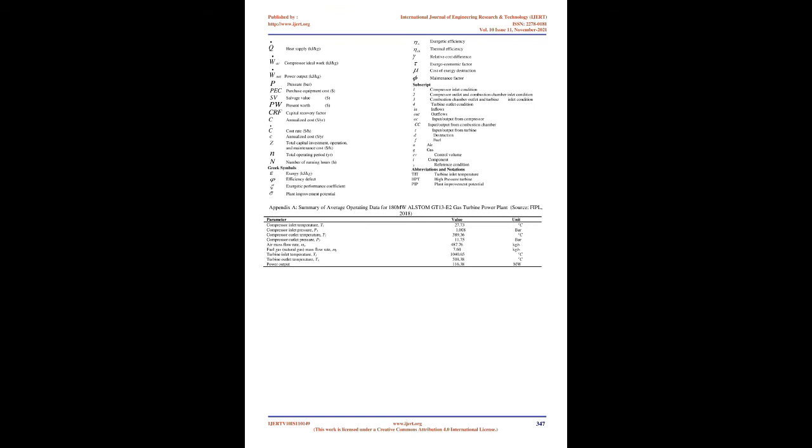The combustion chamber's high value of the relative cost index, 27.87%, and low value of the Exergo-Economic factor, 1.81%, indicate the high rate of exergy destruction associated with this component. By increasing the compressor outlet temperature and turbine inlet temperature, the cost of exergy destruction of the combustion chamber and other components is reduced. This, however, results in a slight increase in capital investment, operation, and maintenance costs.